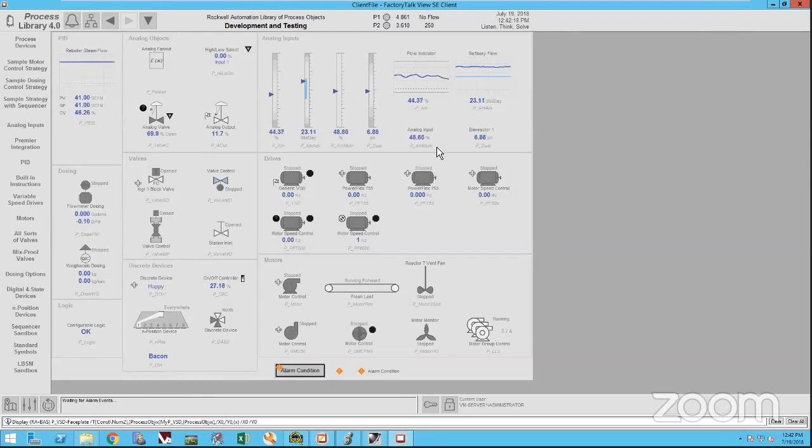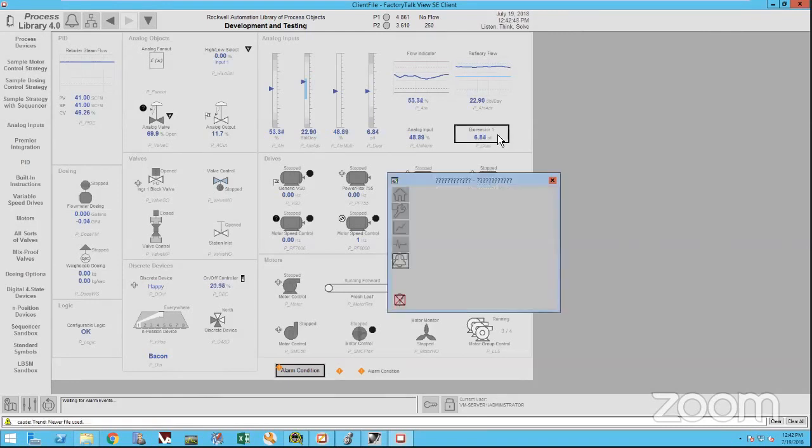And now they added a couple different functionality pieces. Every single one of these is tied into a global object. So what that means is inside of the HMI, there's a little template design that you just drop into the screen. All you have to do is associate it with the name of the add-on instruction. So if I call it pump 101, I just give it a name, pump 101. I don't have to worry about any of the points inside of this guy. Everything is auto-populated for me as long as I tie it into the name. If you're using application code manager, as I said earlier, you are now doing it automatically without having to do that step on it. So again, we're getting down on that piece.